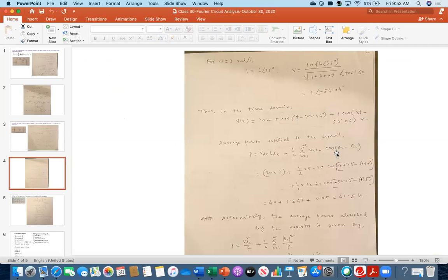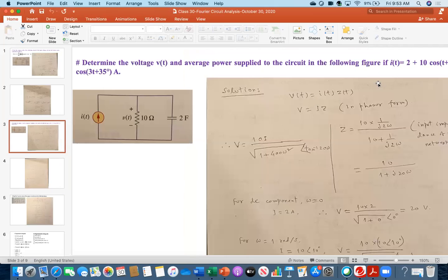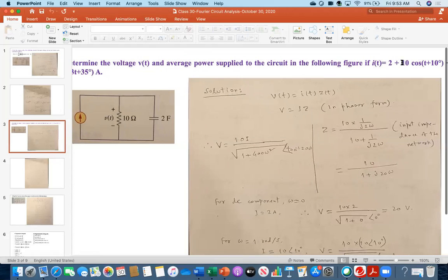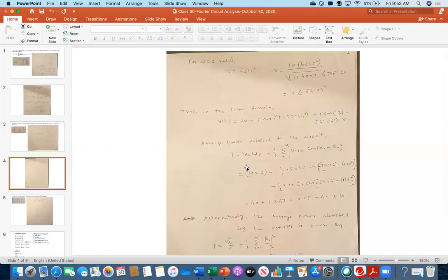If you remember that power calculation chapter, this has Vn, which means the magnitude of V. Now I am dealing with this term and the corresponding current second term, this one. Look, everybody, this one. So the current magnitude is I, which is 10, and my voltage magnitude here is 5. So I have V5 times the current, and then the meaning of this one: cosine of voltage angle minus current angle.